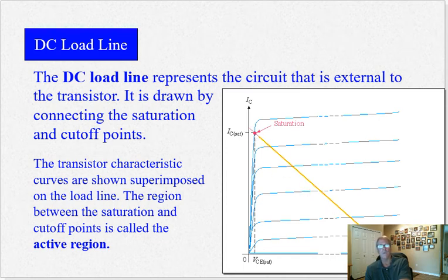Now this is called a load line. And what I think is interesting about this is the way amplifiers work is that you kind of walk up and down this load line. If you increase the base current, you see how it hits these points? Well, this is a linear relationship. And as you increase the base current, you decrease VCE and increase IC